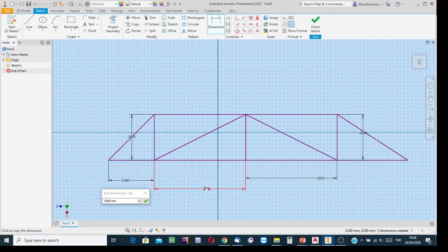And while you're taking the strength of materials course, you're going to learn some other things. For instance, especially for the vertical members, determining the strength of the member, and correspondingly selecting the cross section in the necessary size. We consider not only the normal stress, but for the vertically oriented members, the other important thing is the stability of the member. There may be unexpected deflections under the action of the vertical loading. So consider not only normal stress but also the stability of the member.